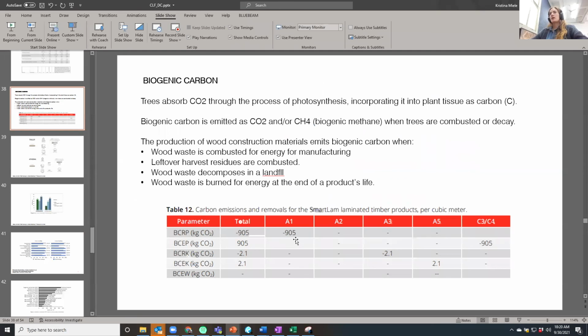So that's saying like, it all has to come to zero basically. It's when you start to look at alternate options for end of life where you can start to bring back some of the negatives, like, and allow yourself. So the more conservative way to look at it is to just exclude biogenic carbon altogether and just look at the manufacturing impacts of timber as a material.